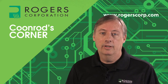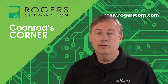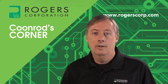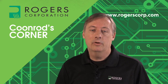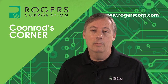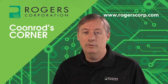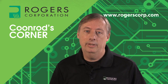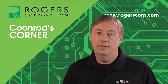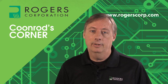Minimizing the temperature of the circuit is important for reliability and also for RF stability. However, there are several other topics that need to be considered for RF stability and reliability. One of them is TCDk, thermal coefficient of dielectric constant, and I'll explain that a little more as we go along. Then moisture absorption can be another concern. Short-term high temperature exposure such as soldering, assembly, or rework is generally not an issue, but there are some exceptions there. And then finally, long-term thermal aging. I'll also give some information on that as well.